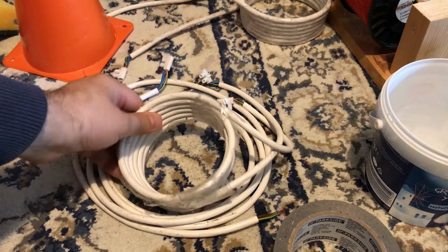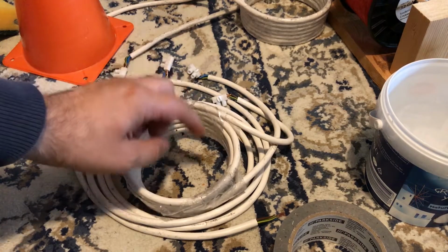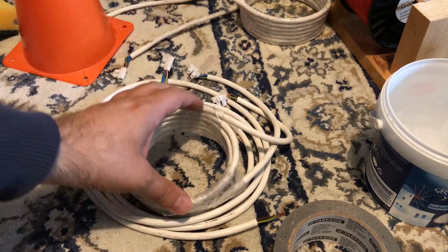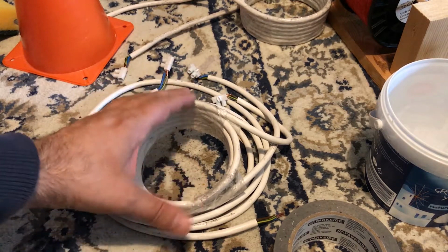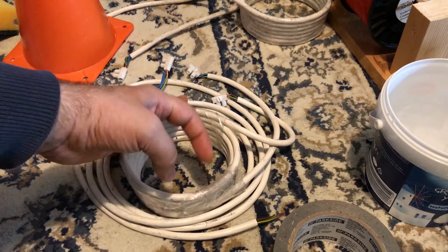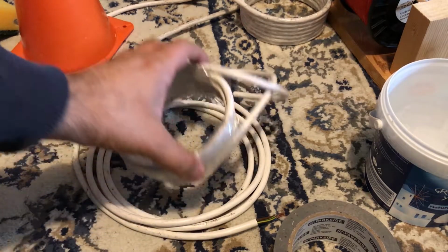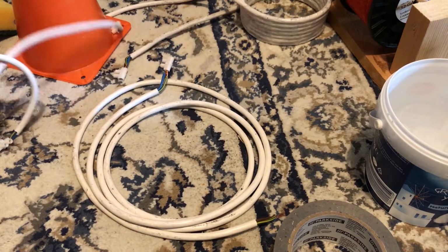Now the first coil that I made was this one, but I quickly found that a lot of sparks happen between the secondary and primary, because the diameter of the secondary is very large, and almost no distance was available. So there was a spark between the secondary and primary. So I decided to increase the diameter. And then I gave up the conical shape because I didn't have another structure to wrap it around.